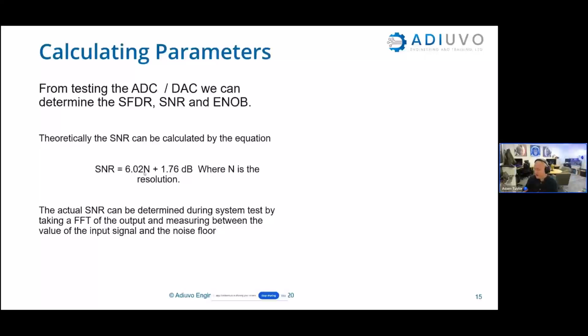A lot of this also comes down to PCB layout, power integrity, signal integrity, things way beyond the scope of this talk. But it's not unusual to put a design in the FPGA when you're bringing up or designing these boards to capture this data, to allow you to work out what is actually going on in your system, and whether you have issues or whether you're meeting your requirements or not.